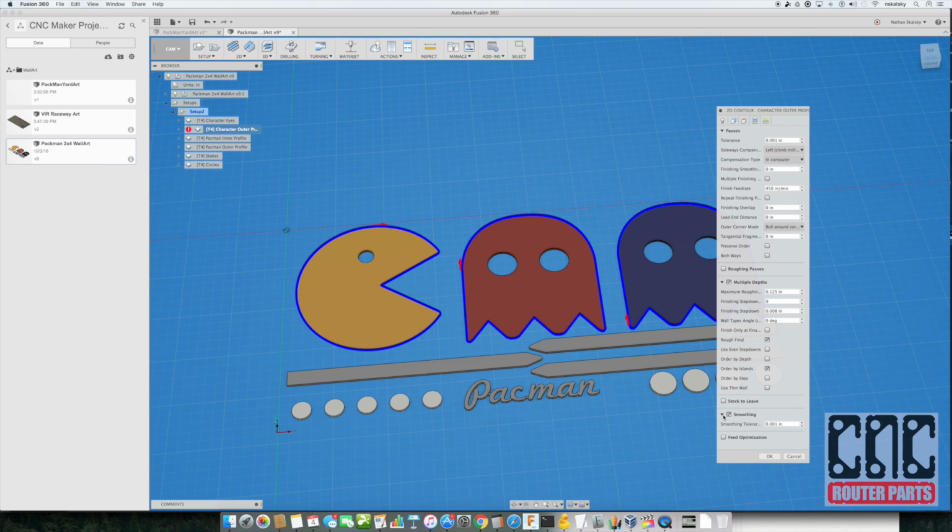inch, and enable smoothing. And this is where things can get a bit counterintuitive. But generally speaking, the tighter your tolerance is, the more data the smoothing feature will have to generate good arc fitments, and that should not slow down your machine. The upshot of this is that if your machine is not hitting your program feed rate and you're using smoother and want to tune further, try adjusting the smoothing tolerance, making it looser, while leaving the overall tolerance field at the top tight, in this case 1/1000th of an inch.